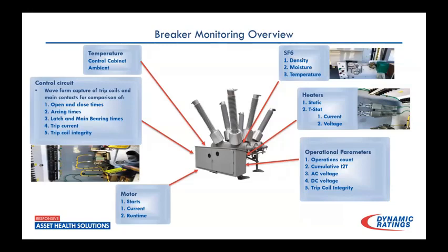I feel like you really got to consider temperatures as one of the big things to be looked at, and that would include ambient temperature as well as cabinet temperature and gas temperature, to understand what's happening when it gets cold at night and you're calling crews in, you're getting these calls about leaks. Is it a leak or is it a temperature related thing? Are my tank heaters working? Are my cabinet heaters working like they should? Because that results in condensation forming in cabinets.